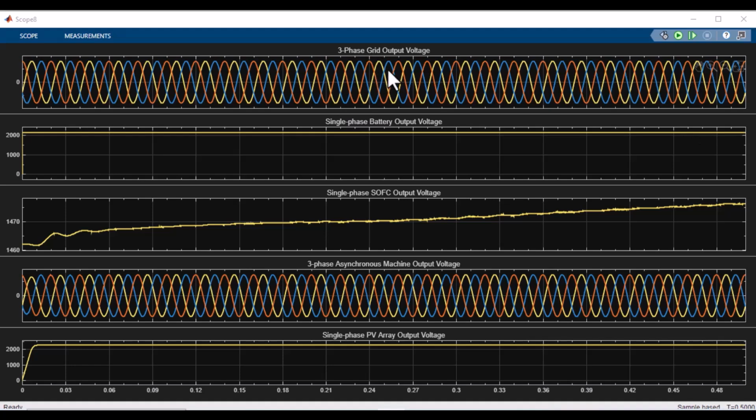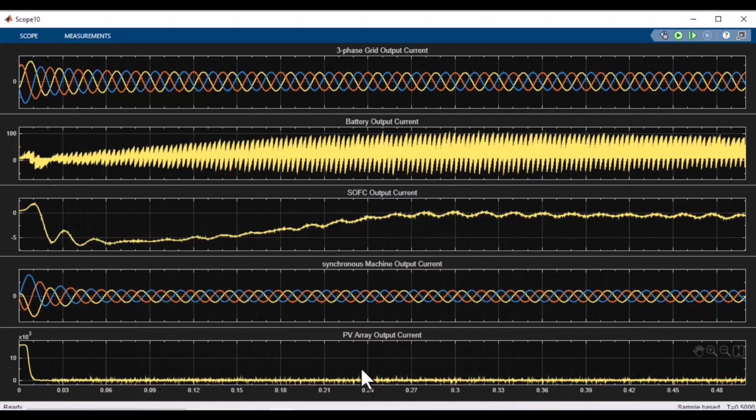You can see here there are some changes in these signals. The current waveform is going to 0. It's not providing current to the load, so it goes off the controller. I told you before that the controller is doing all these things. I have run it for 0.5 seconds, but it should be more than 10 or 20 seconds for steady analysis. But it was heavy, so I just tested for 0.5 seconds just to show you the output in a small